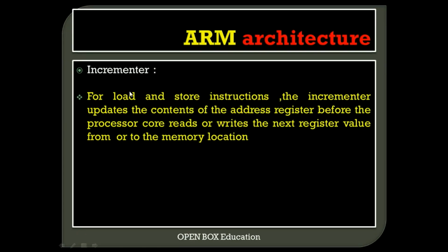And next one is the incrementer. For load and store instructions, the incrementer updates the contents of the address register before the processor core reads or writes the next register value from R to the memory location. So here the incrementer will do that for load and store instructions. This is about the functioning of this incrementer.